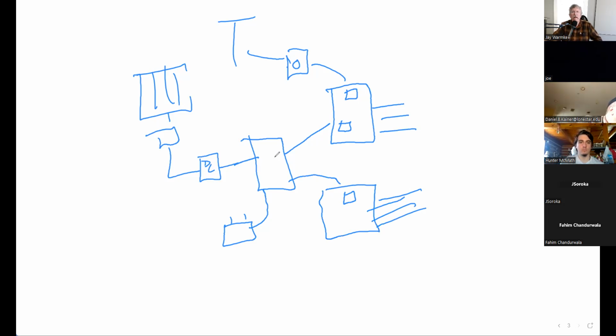Now, within here is an auto disconnect switch. So there's a sensor wire that's sensing. Assuming the grid is up, power is flowing through here and it's going to this breaker box. It's flowing through both of them. If I have enough power from my array, it's servicing here. If there's more power than I need, it's going out on the grid. If I don't have enough power, some of it's flowing this way, some of it's flowing this way. I can set things up where I can use the battery if I needed to, that kind of thing.